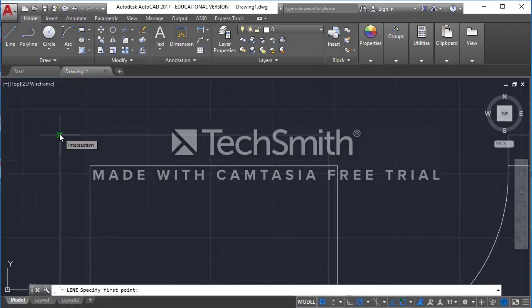So if I go here, and I move my mouse over, I'm going to just type in 1 foot 6 inches, and notice that it now starts my line at that dimension. So I don't need to guess, or try to move my cursor very carefully along that edge until I see exactly 1 foot 6.